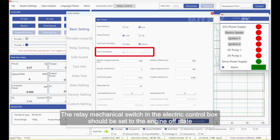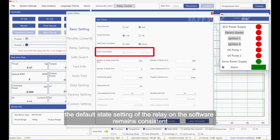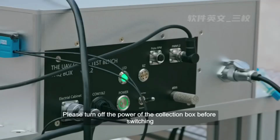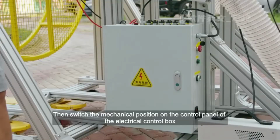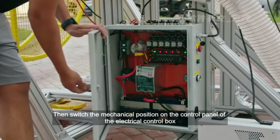In closed loop mode, the relay mechanical switch in the electric control box should be set to the engine off state. That is, the ECU is powered, and the igniter is in the off state. At the same time, the default state setting of the relay in the software must remain consistent. Open loop or closed loop mode switching: please turn off the power of the collection box before switching. Then switch the mechanical position on the control panel of the electrical control box.